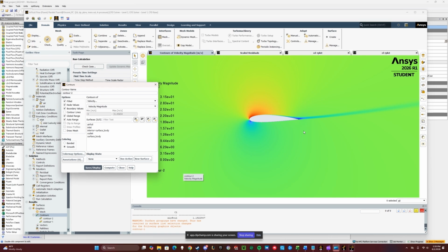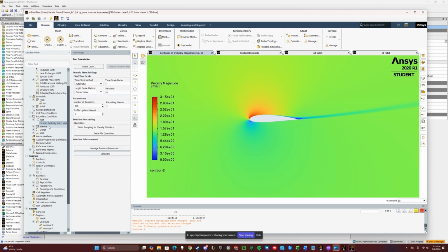So to summarize what you need to do next, you just need to go through each angle of attack from -3 to 21 in intervals of 3. At each angle of attack, you calculate your inlet velocity for your x and y values, your unit vector for lift, and your unit vector for drag. And then type those into your inlet velocity parameter right here and into your report definition CD and CL. And then you run it for each one of these angles and gather CD and CL.